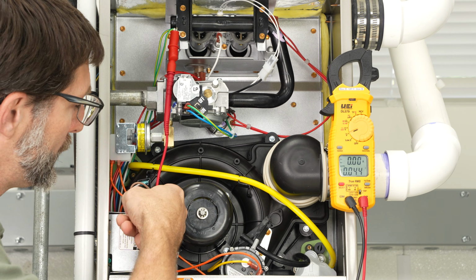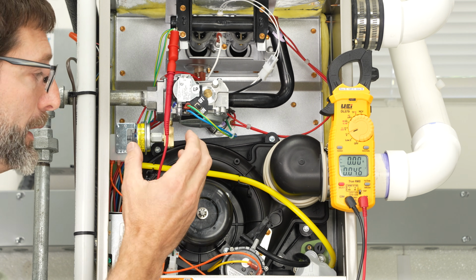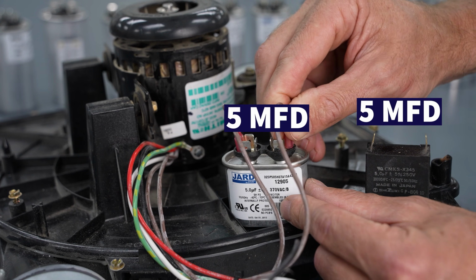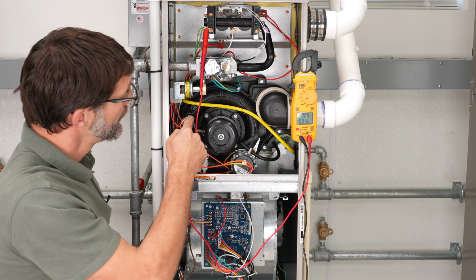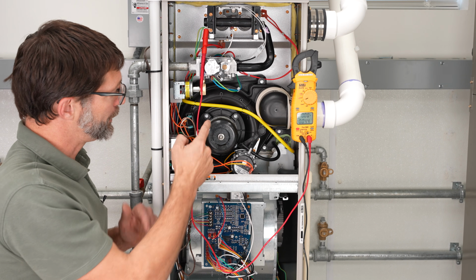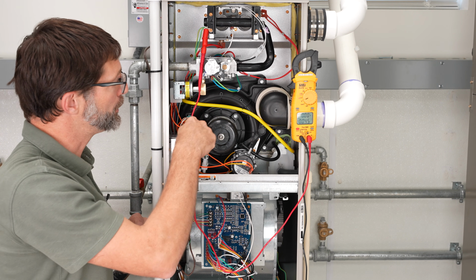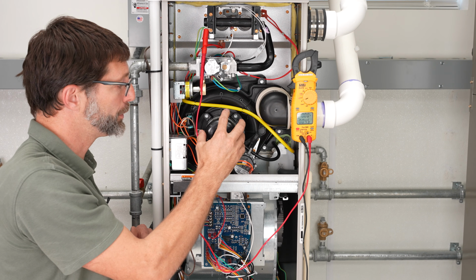Some look like this little black box, and some are using aluminum capacitors. And so you could replace this with an aluminum one as long as it has the same microfarad reading and a higher voltage rating. If you don't know the microfarad rating, you typically can see it on the rating plate of the inducer motor itself.